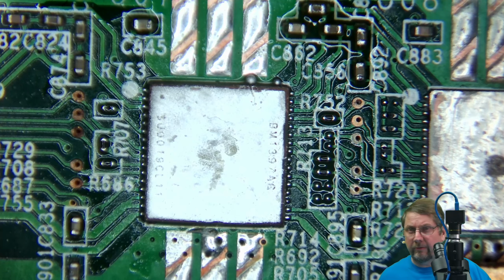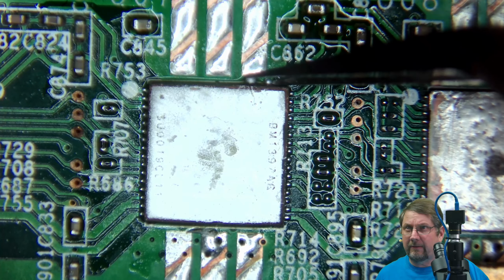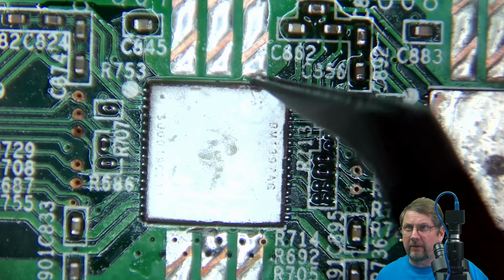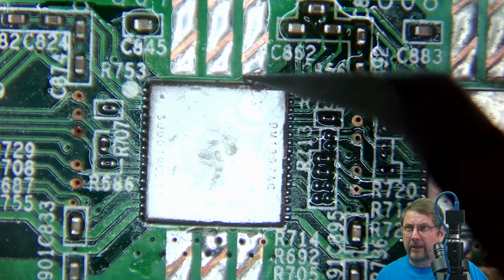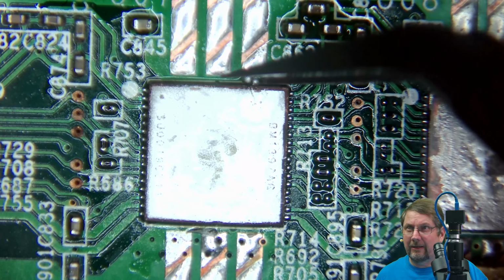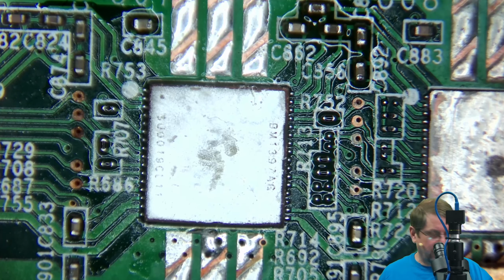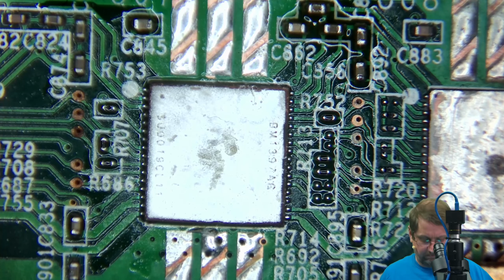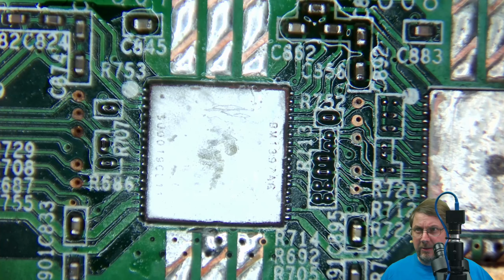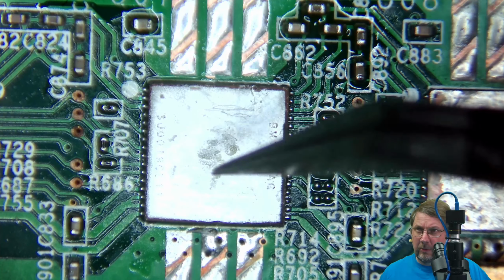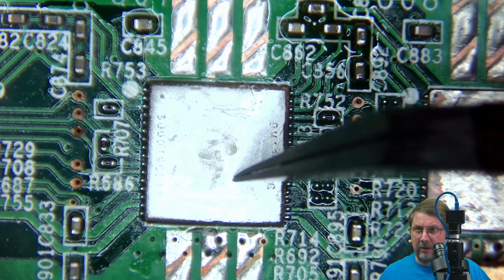Okay, so you may have noticed these solder balls that came about this time. I put a little bit too much solder on the positive pad, and I'm trying to get those solder balls off. Now there we go. I put too much solder on the top solder pad right underneath here, so I knew when I put the chip down, it didn't want to really go all the way down.